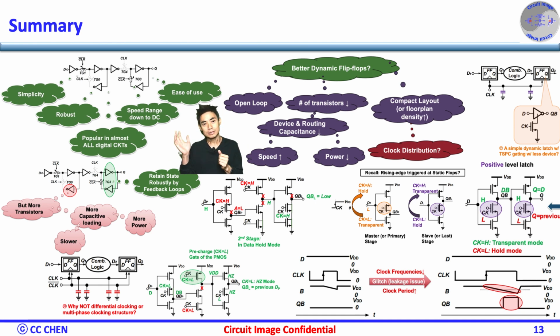We show the TSPC latch and TSPC flops from the design idea for its operations. According to those concepts, you should be able to come up with your own and other similar improved dynamic flops. But you must watch out for their limitations or pitfalls in design at very low clock frequencies because of the leakage from the transistors.